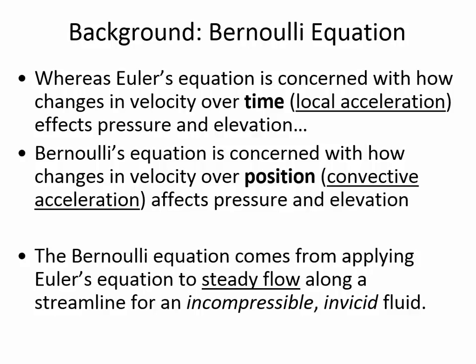But let's look at it the same way we did before. When we were talking about incompressible, we said, well, between gases and liquids, which is like the worst violation? And it's gases, because of the two, liquids are more incompressible. So we'll get some more accuracy as far as this assumption is required when we use liquids. But then viscosity, maybe you haven't developed a sense for it yet, but in the back of your book it has tables of viscosity, and gas viscosities are much, much lower than liquid viscosities.